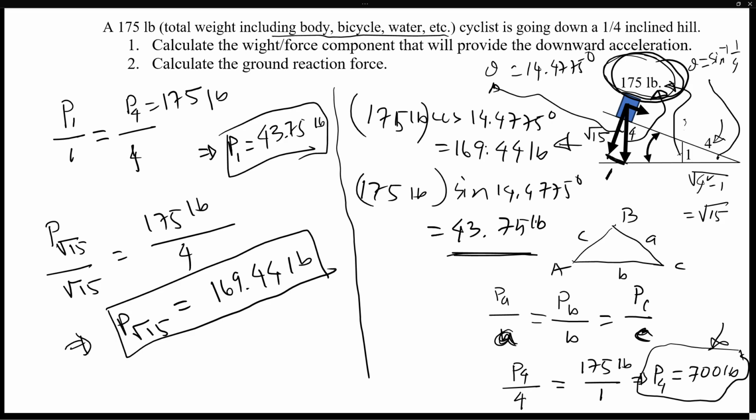So whether you use the sine law or the right triangle formulas, you need to understand what force it is. Is it a component or is the resultant given? Based on that, you have to assign these different sides in relation to the force provided. Then it doesn't matter whether you use the sine law or resolving forces, both will provide you the correct answer.